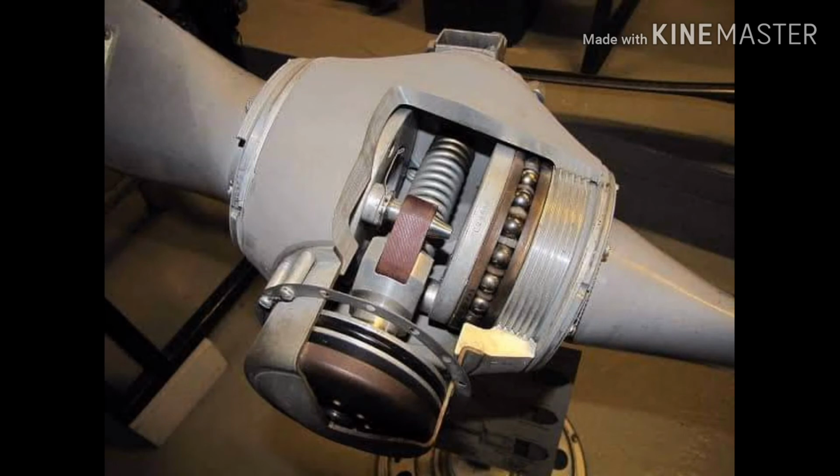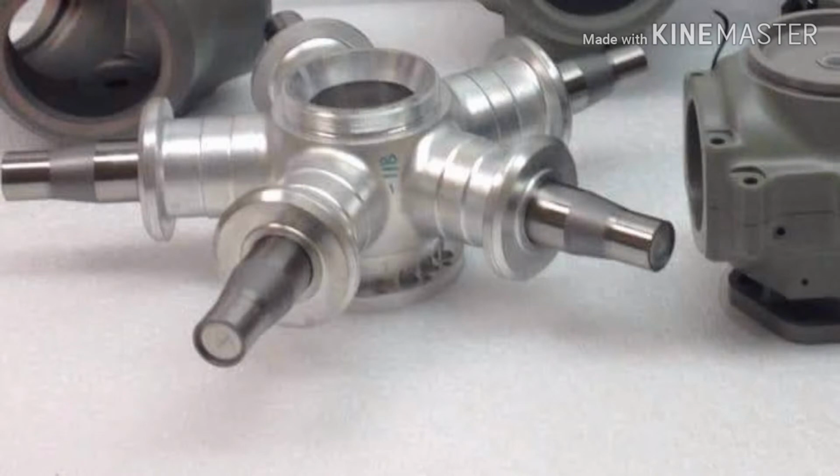High friction in hub parts. High friction in the pitch change mechanism in the hub causes the pitch to change slowly and may prevent the propeller from feathering. This condition must be resolved by a certified propeller shop. The cause for high friction in hub parts is corrosion.